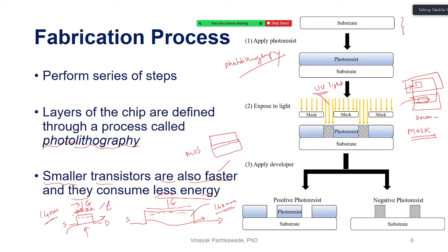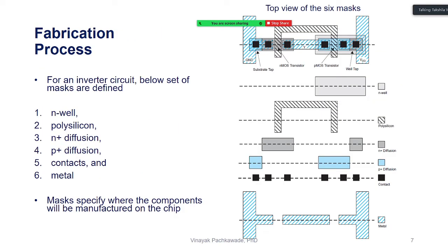MOS. This is metal or polysilicon. We know that nowadays people use polysilicon for a gate terminal, but we are still calling it the MOS. This terminology keeps on continuing. This is SiO2, simply a glass or oxide. So this is insulator, this is conductor, and the middle layer is insulator, and this is semiconductor. That's why we call it the metal oxide semiconductor, MOS.